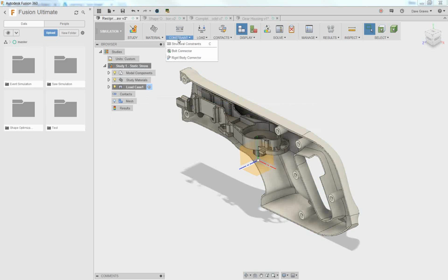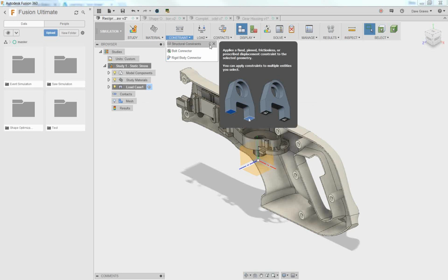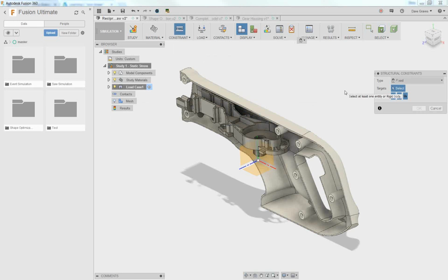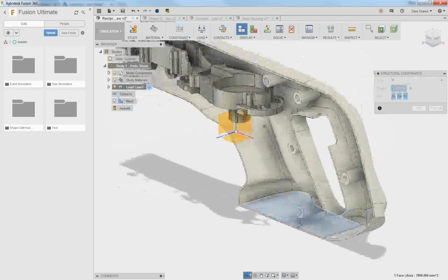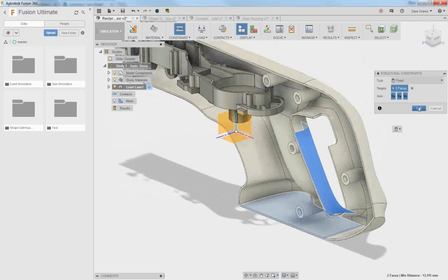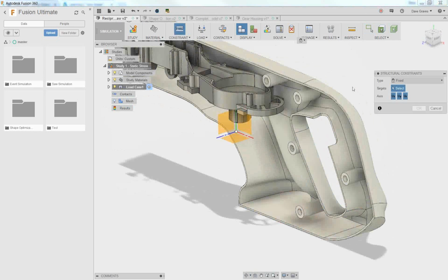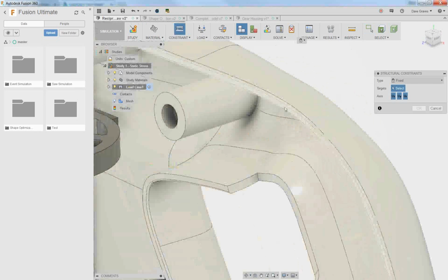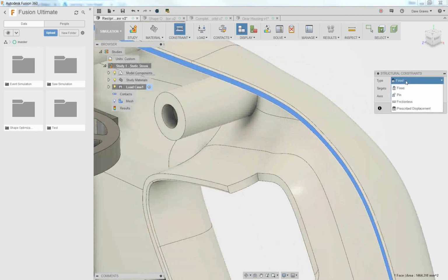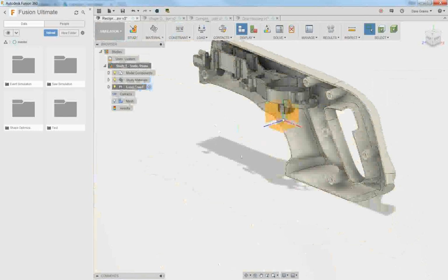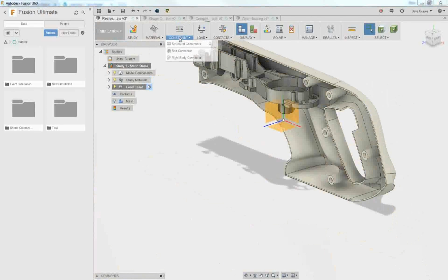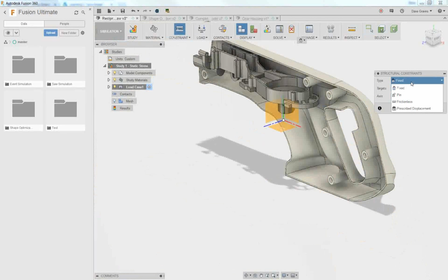Now I'm going to go to constraints. I don't know if you see this, there's a little C right here. That's a hotkey. So if I hit C on my keyboard, the constraint menu comes up. For this model, I'm just going to fix a couple parts of my handle here. And then I have some symmetry, so I can pick this symmetry edge. I could specify which way the faces are constrained, but I just like to use this frictionless constraint. Got my constraints set up. These are all for people that do simulation.